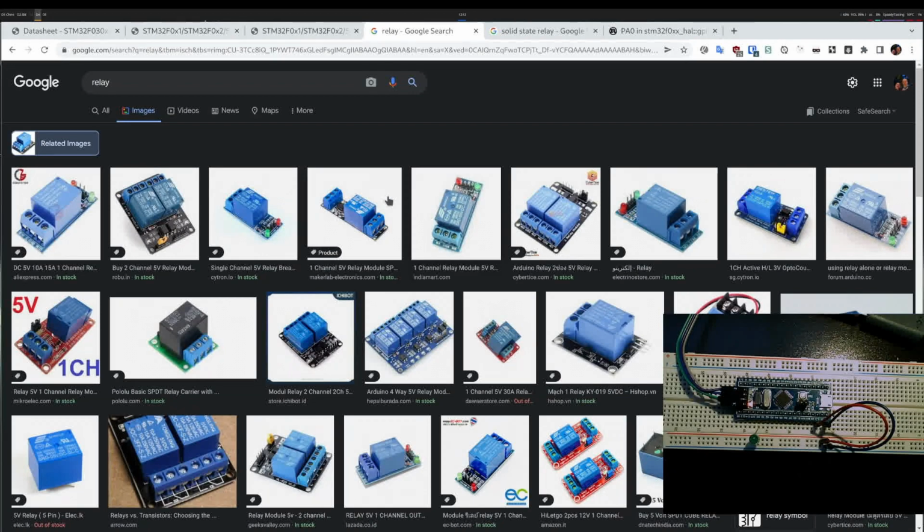The other thing that you have to take care about is what is the voltage required to turn them on and off. The items that I have, and they are generally available, are 5 volt. So this means you need some sort of a logic level shifter if you use a microcontroller like I do, which is 3.3 volt. And the other option that you can use is a MOSFET. So this acts like a switch. It will look kind of like this. And it does work. However, also for MOSFETs, they have a trigger voltage. So you have to get a logic level MOSFET so that you can actually trigger bigger loads.